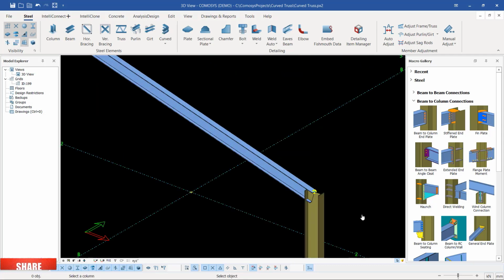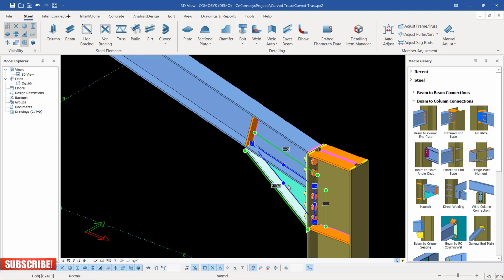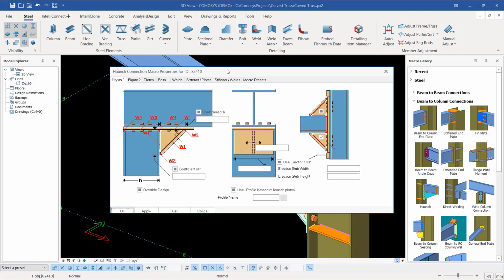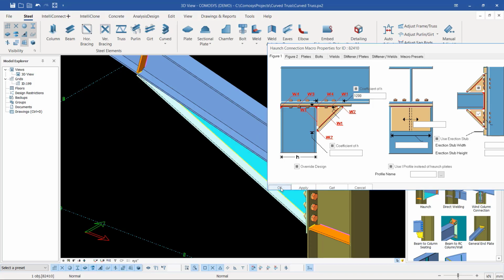So straight away start creating haunch connections right there. And maybe you want to adjust the haunch length, then double tap letter M, then enter on your keyboard. So this will bring the setting dialog box. So I'll come here and adjust this to 2.2 to 1.2 and enter that, and by clicking apply, then that.